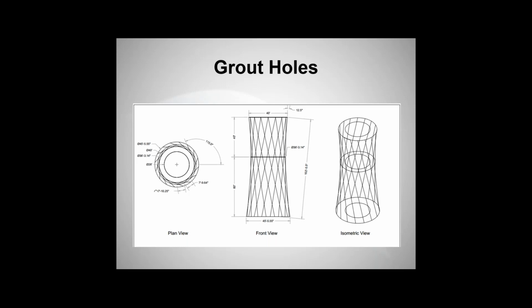Essentially, once a shaft gets too deep, which depending on the exact geology is typically somewhere between 200 and 300 feet, but it depends on the overburden also, it becomes very hard to do this from the surface. It's a possibility from underground, but just a consideration. Overburden and shaft depth play into your ability to angle the holes and address the fractures through this means.